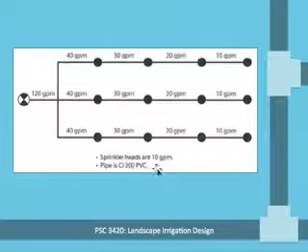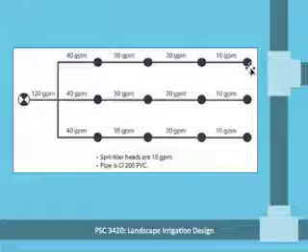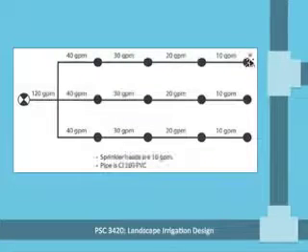Again, given here, sprinkler heads are requiring 10 gallons per minute. So the furthest sprinkler on each lateral requires 10 gallons per minute of water, and 10 gallons per minute are what are going to be needed to flow in this last section of pipe. And then just like we did in the previous example, you just sum those, they're cumulative as you move back toward the valve. So here on each of these laterals where there are 4 sprinklers requiring 10 gallons per minute, a total of 40 gallons per minute is going to be required at the beginning to supply all of those sprinklers.